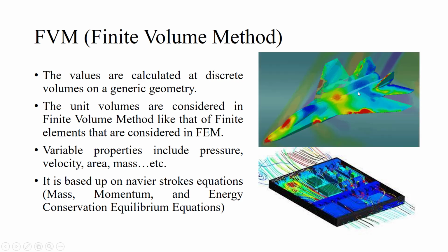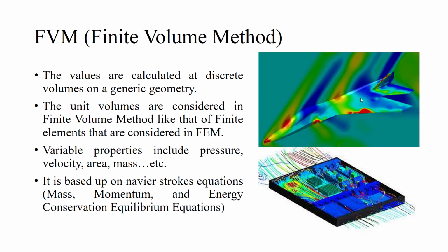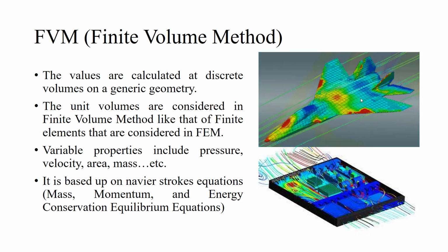See here in this picture, you will be able to see that this particular geometry is being divided into a number of cubical volumes. Likewise, different variables such as pressure, velocity, area, mass, etc. can be calculated, and then this particular method is based upon the Navier-Stokes equation, like say mass, momentum and energy conservation equilibrium equations.